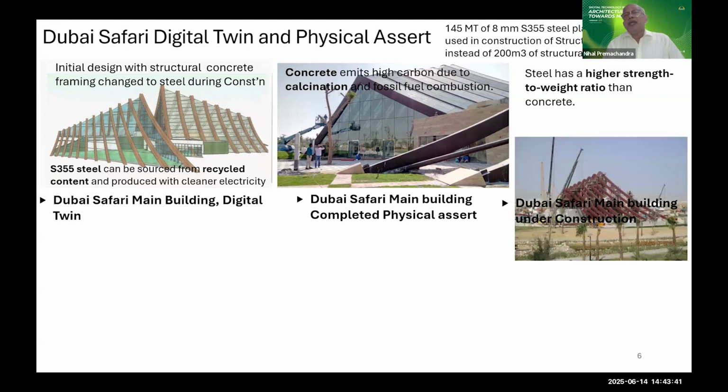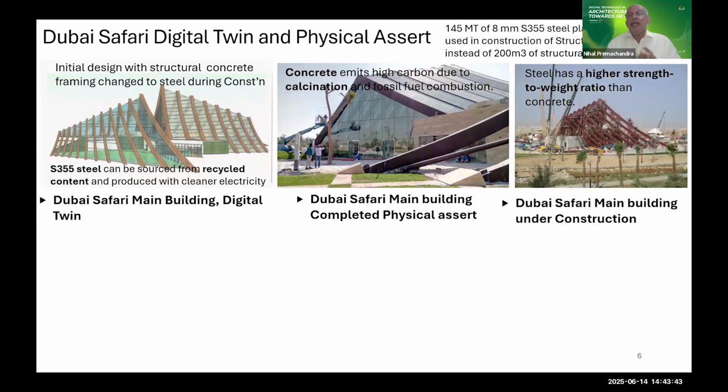And then here you can see that I have done my installations of framing. This framing is very light. I was using 8 millimeter thick plate. Now, if it is a box section and 8 millimeter thick plates, that will reduce the foundation load. So I'm using a lighter foundation than a normal foundation. So I'm saving materials, I'm saving energy, I'm getting close to my net zero energy building targets.